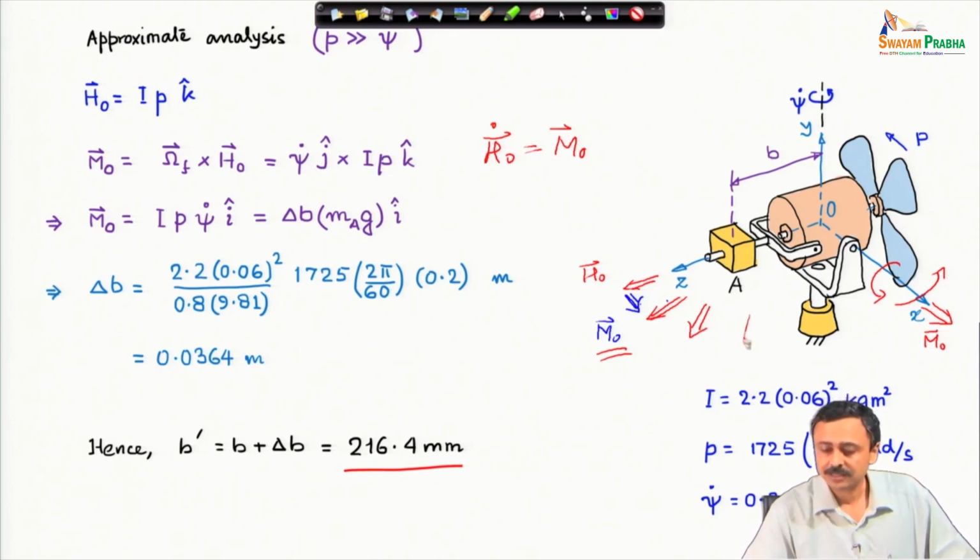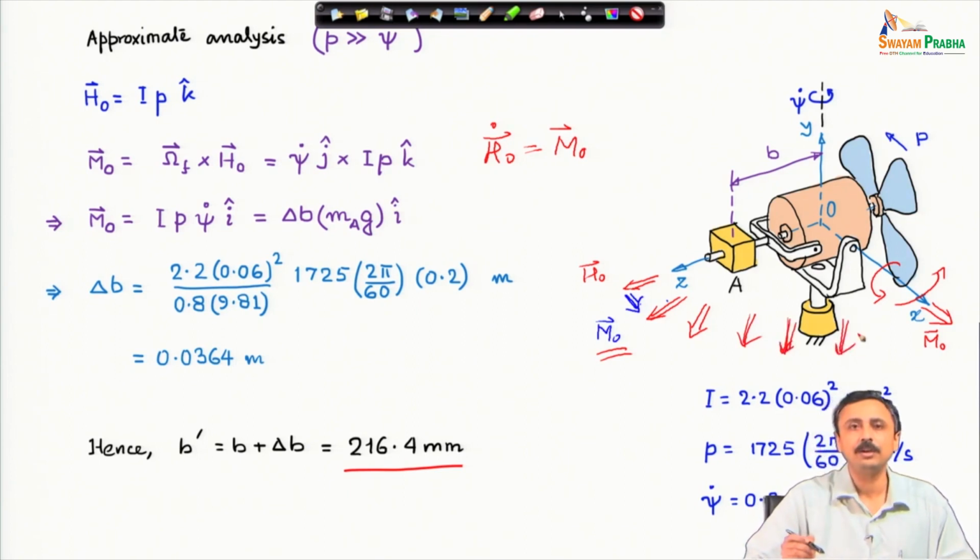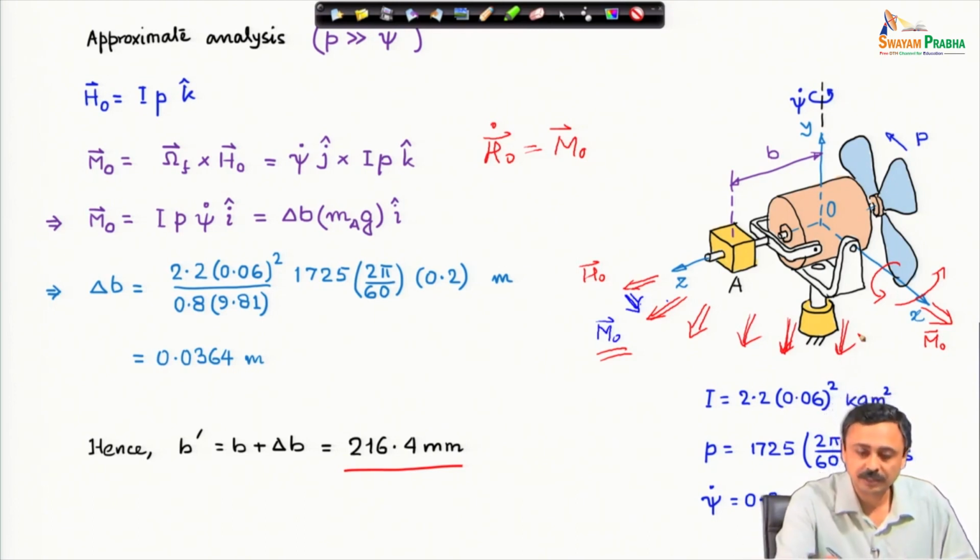Therefore, this whole assembly is going to keep rotating. So, this should give you a geometric idea why providing a moment about the x axis, which is rotating with the assembly, continuously rotates the angular momentum vector.